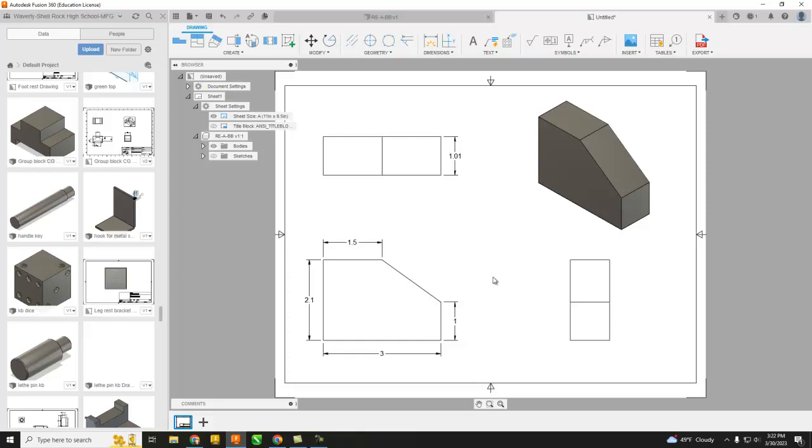All right, if you're interested in an angle, it'll do that too. Click on it, go ahead and click here, click on another line, and look what that thing starts to do for you. It starts to get you the inside angle, could get you this outside angle, this angle, just wherever you move the mouse to is what it's going to do. Okay? So I kind of like that placement right there. Looks cool. Alright, so those are the dimensions that you need for this particular part.